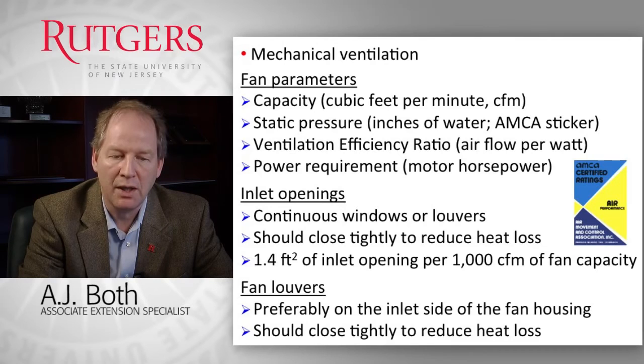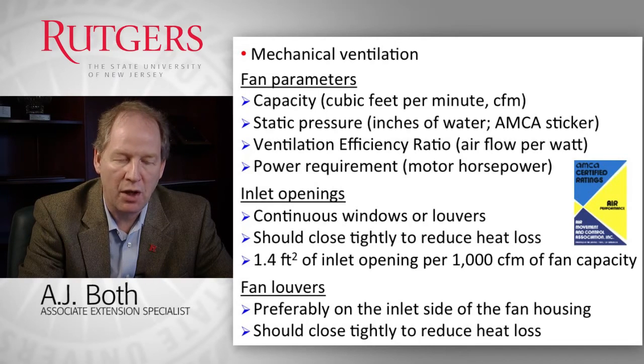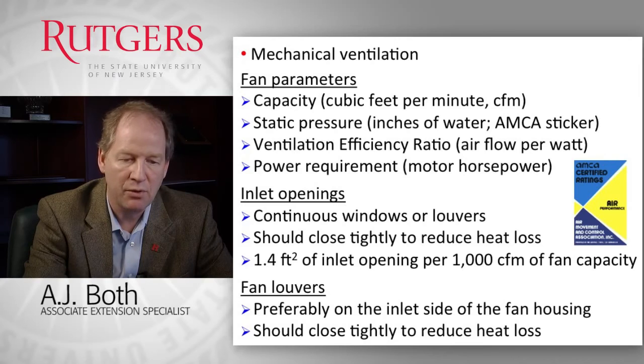So with this number, you can approximate how much opening area you need given a certain overall fan capacity that you install in a mechanical ventilation system. Most fans are equipped with louvers to shut off when the fan is not running. We typically prefer to have those louvers installed on the inside of the fan housing, so on the upstream side of the fan, so as to reduce the resistance of airflow throughout the entire fan system. And they should obviously close tightly to reduce energy loss, as I mentioned before.